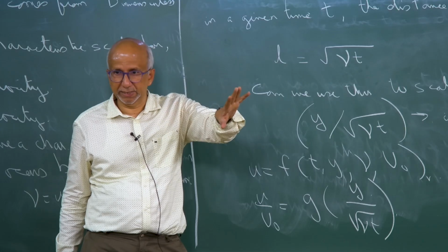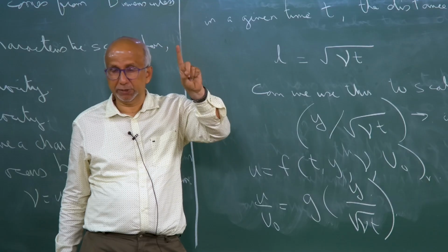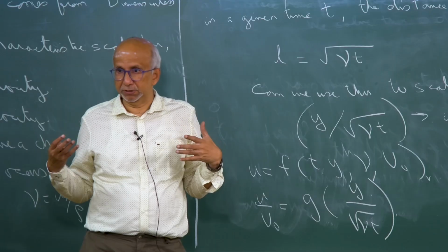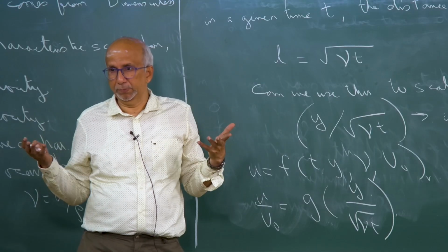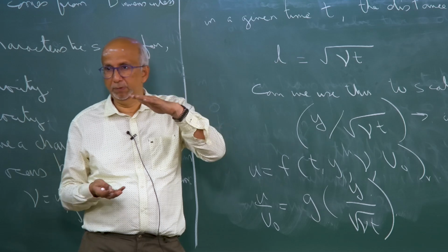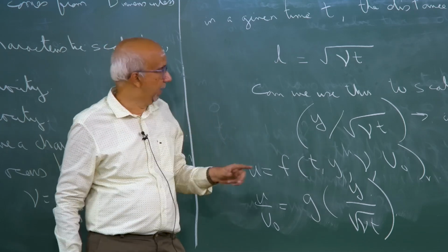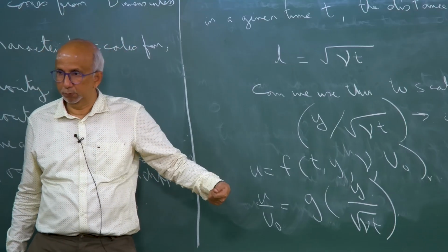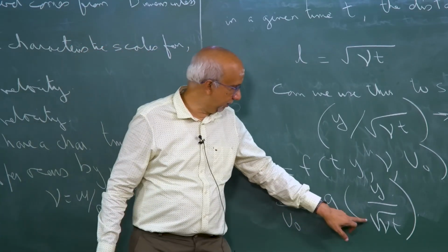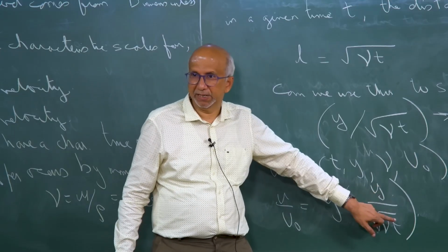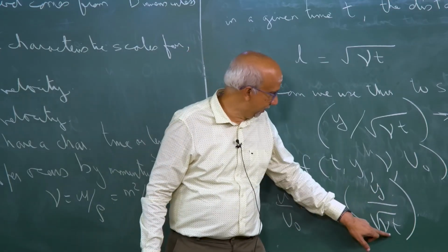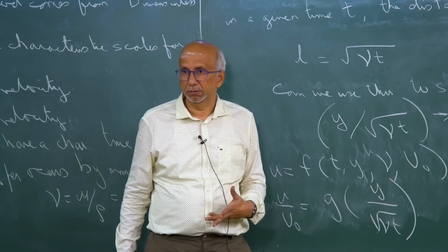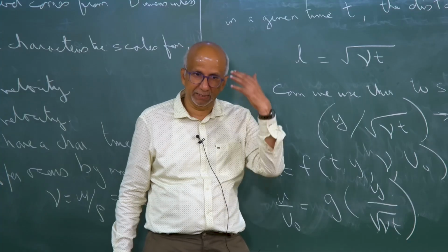But this making it dimensionless is different from the classical methods that we have been using so far. I want you to understand that, okay, because whenever I use characteristic scales, there were parameters in the problem which I could change, like diameter of the pipe, okay, gap between plates. They are parameters, like the velocity which I can pull with. But here I can only change the fluid, but I can't change this guy, but this is a scale. So, this is some scale, but this scale contains time, which is an independent variable. So, I can't really control that.